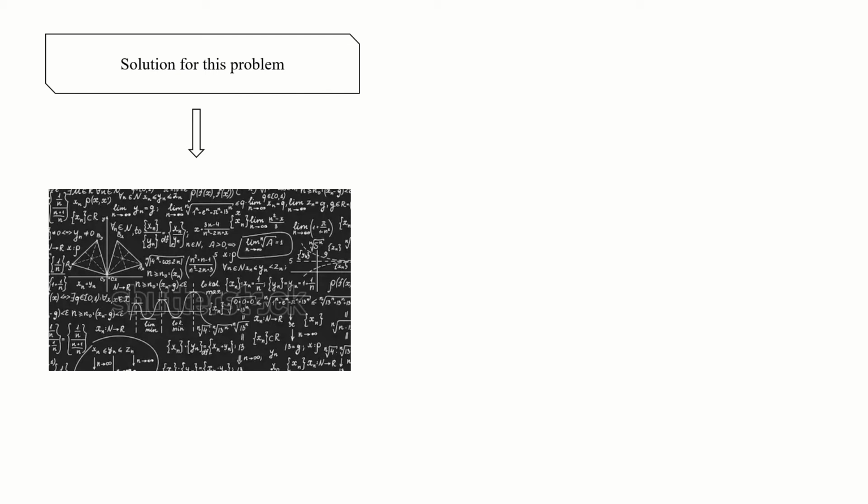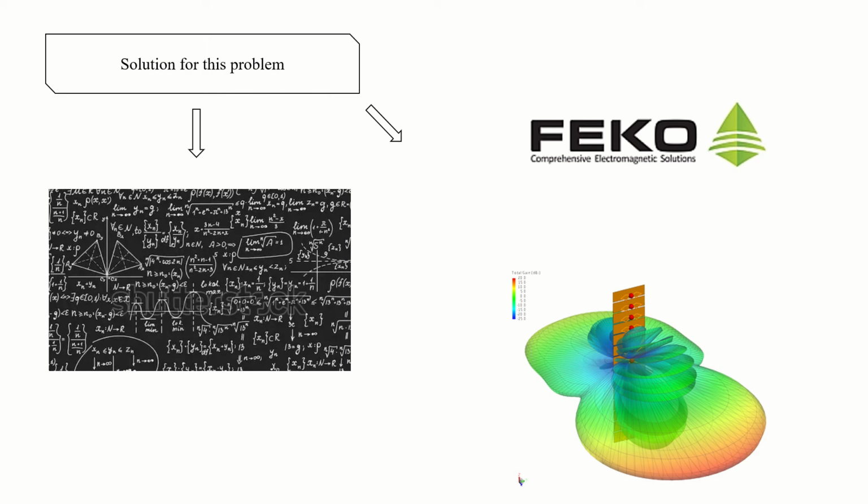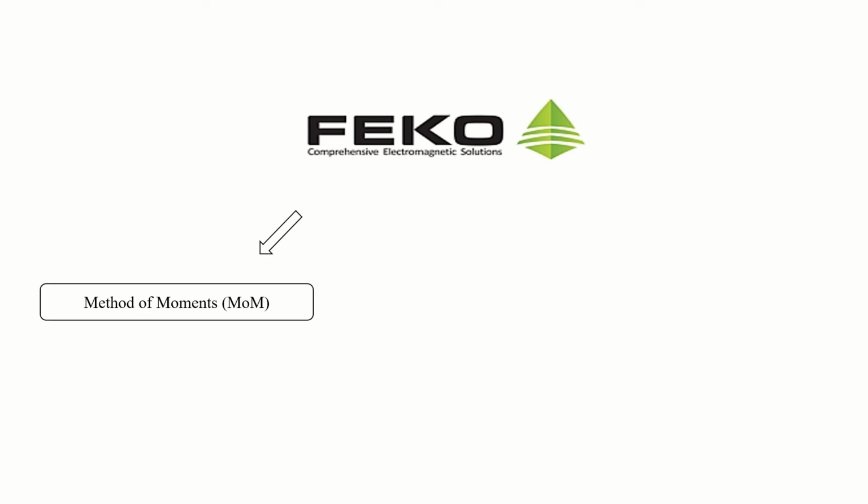But this equation is not finalized. I'll be using an electromagnetic simulator named FEKO to analyze the radiation pattern, input impedance, gain, electric fields, near field, and return loss. Why did I choose FEKO? It is because FEKO is the best option for the process of designing an antenna, as the software can be used for simulating our desired antenna in multiple environments including seawater conditions. The concept of the software is based on the integral formulation of Maxwell's equations using the method of moments (MoM).